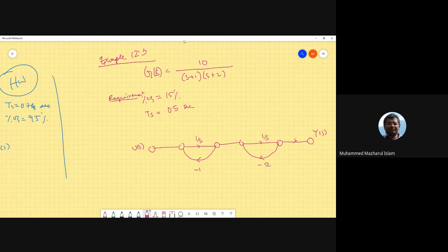So let's place the arrows. This is the gain of 1, gain of 1. Now let's name the state variables. This one was x2 dot, this one was x1 dot. So therefore, the other nodes would be x1 and x2, as you can understand. The gain here would be 10, the upper gain.